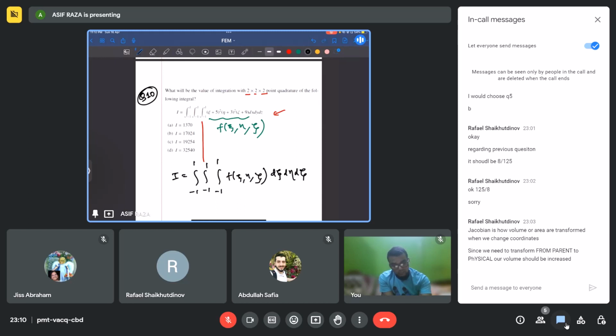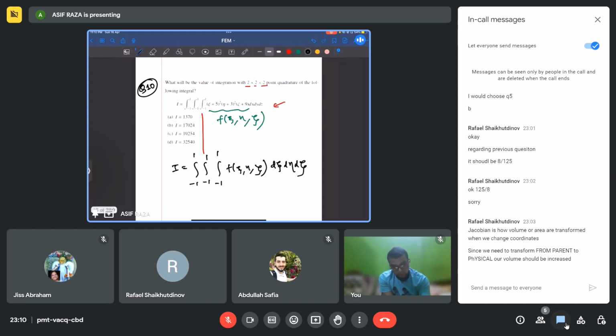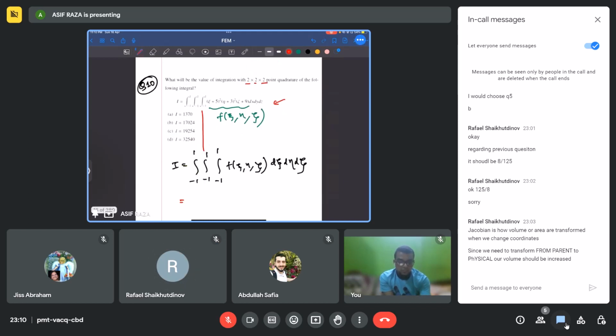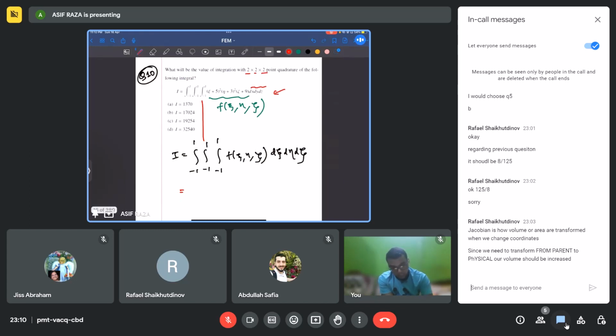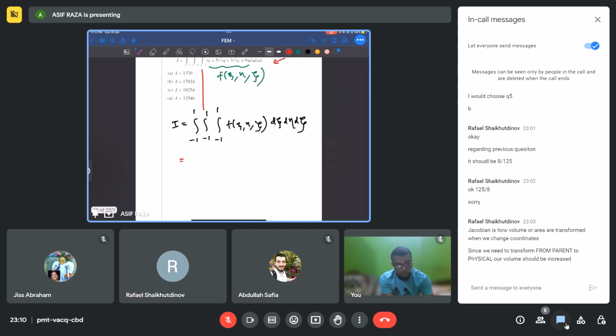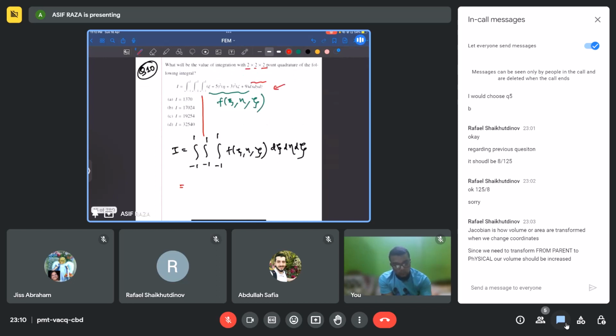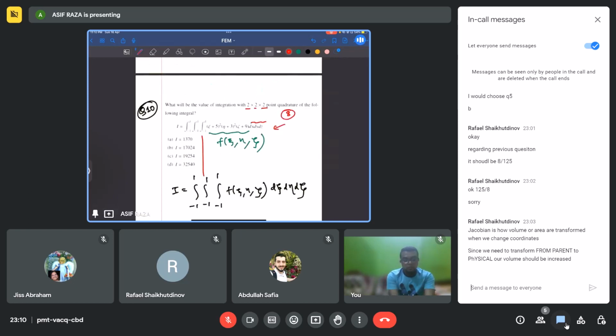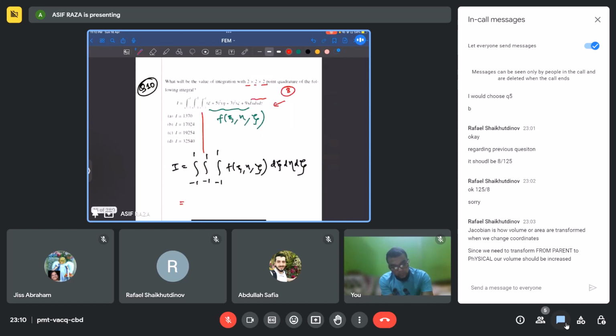Okay. I don't think there is a misprint. I do think that it should be d psi d eta d zeta. Then what needs to be done is we have a 2 by 2 by 2 point quadrature rule, right? So in total it will be 8 points, and in all three axes we are following the 2-point quadrature rule.